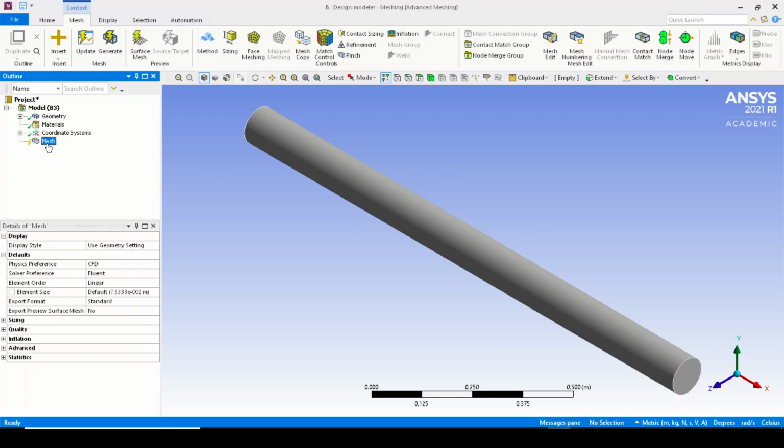Now coming to the bottom point, we have to perform the mesh over here. As I mentioned, we are just dividing the domain, and the ANSYS meshing module has very basic meshing features. If you want a very clean mesh, you can create it here, but if your case is complex, you had better use other meshing software such as ICEM CFD. But if you are able to create a normal tetrahedron mesh, an unstructured mesh in simple terms, then we can stick with it and perform the simulation.